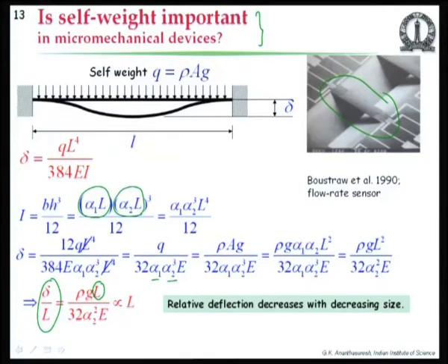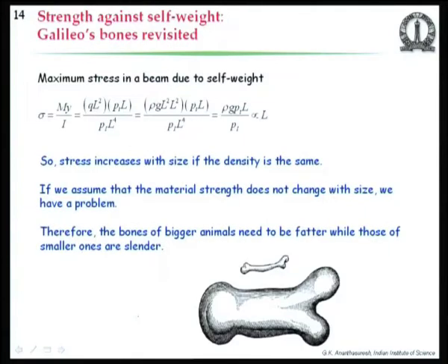If I look at a beam of 1 meter length and a beam of 1 micron length, the 1 micron one is going to have much less relative deflection. So, if I divide this delta deflection by this L, L and capital L in this slide are the same, the relative deflection will be much smaller when you consider the micro one. So, you can say that self weight does not matter so much when it comes to microsystems devices. But then, is inertia force, because weight is inertia force, can it always be neglected?